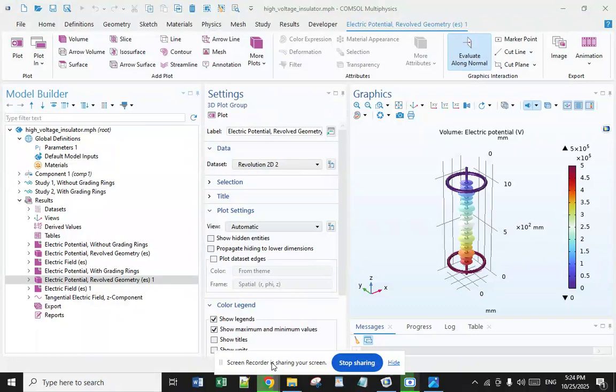These insulators are characterized by their ability to withstand not only the weight of the conductor but also the additional loads caused by wind, ice buildup, and thermal variations. And what are the main characteristics? A suspension insulator typically consists of an assembly of ceramic, porcelain or glass discs that are connected in series by metal fittings.